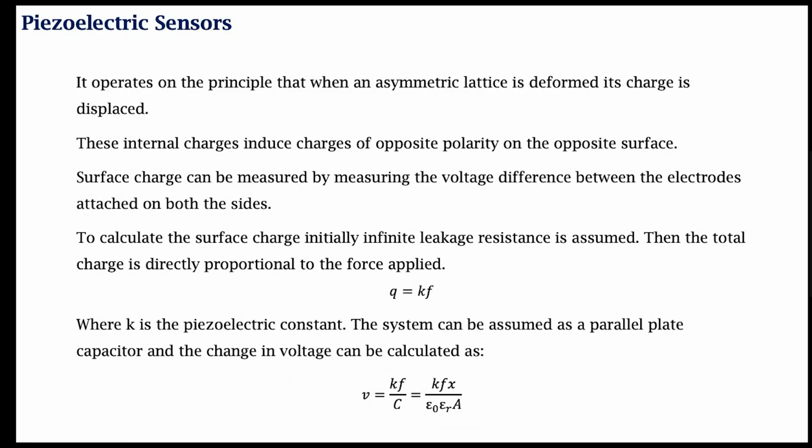And because for piezo systems we use a high input impedance amplifier electronics to process the data, we need to compute the corner frequency or the cutoff frequency, and when you do that, you need to find the effective resistance.